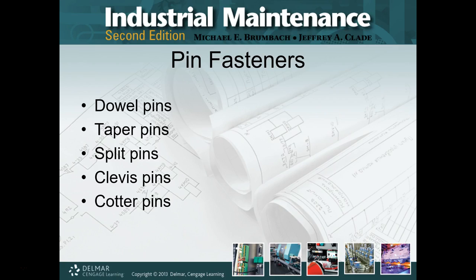And you delicately drive these pins into the hole, and as you are driving them, the split gets compressed, so that little distance closes, because now you're using the rolled pin as a wedge. As you're driving it in, the pin itself is being compressed, but the pin is also pressing against your two pieces, two parts, whatever, and keeping them together once again with this wedge type action. You definitely need a drift punch and a machinist hammer when you are working with rolled split pins.